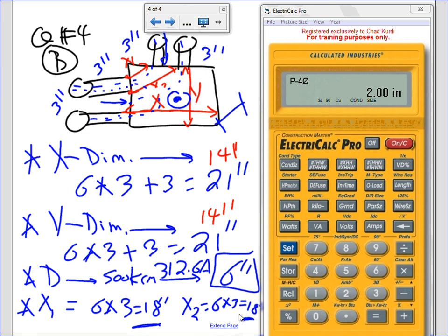So the dimensions X and Y, and the depth continues to be number 6, and the distance between them is 12, and this is also 12. Are you with me? The distance between the conduits containing the same conductors is 12, 12. The dimension of the box is 14 by 14, and the depth of the box is 6. This is for A version. Any question, guys?